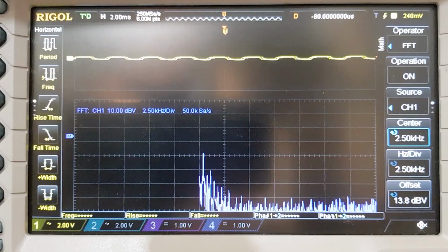So there's one more big problem with this circuit, which is that when the filter is very low compared to the pitch of the sound, the volume of the sound dims a lot. So like, that's really loud, and then as I filter it away, it becomes really quiet. We don't want that. What we want is a thing called an active filter, which simultaneously does the filtering and compensates the gain, so it turns the gain back up afterwards, so we're not having to fiddle around with loads of different knobs to get a consistent volume.